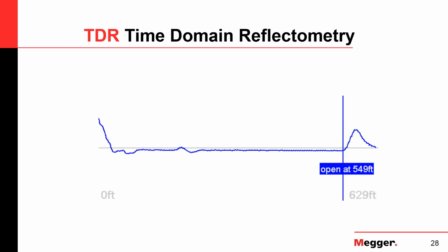Now, how does this look in real life? This is a real life trace, and you can see in front you have some distortion. This is called the characteristic hookup impedance, because you have leads, the distance between the two leads changes until you are actually connected to the cable, and this is reflected by this kind of wave shape to the left, and then nothing happens pretty much.